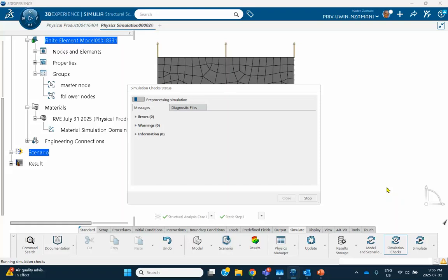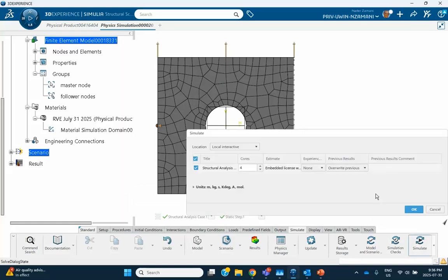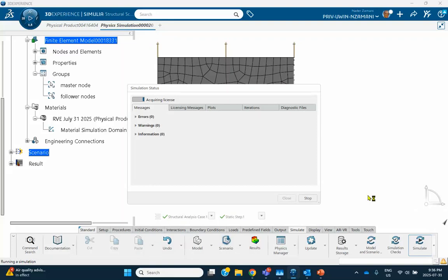There's some stuff that I did that was unnecessary, that seeding stuff and meshing and things like that. I could have used the default triangular shell elements. That's okay. All right, almost done. Very good. Close it. Now we're going to run it. And this thing better stretch upward, and that vertical right side remain a flat plane, a flat line. If you don't do that coupling, it will actually bow. Okay? You'll find out.